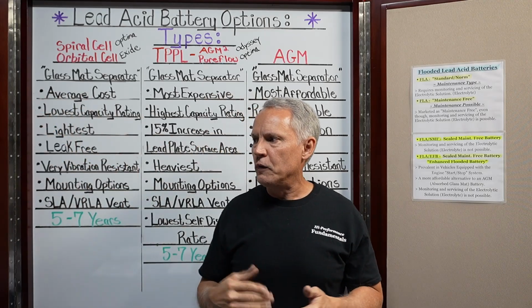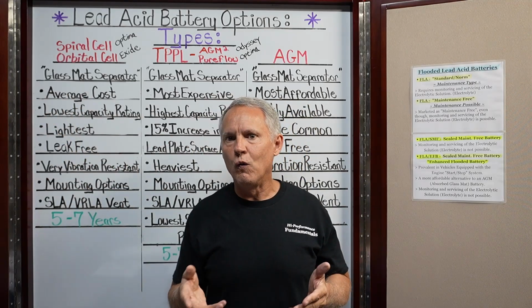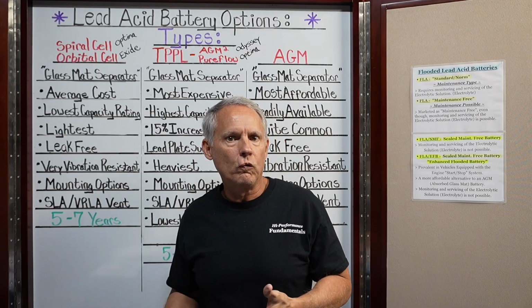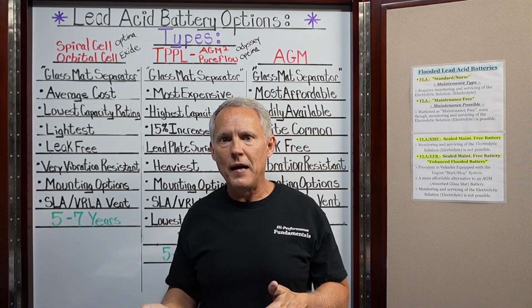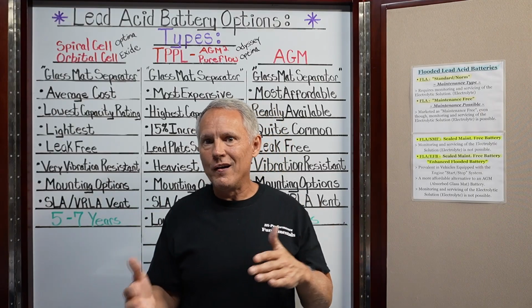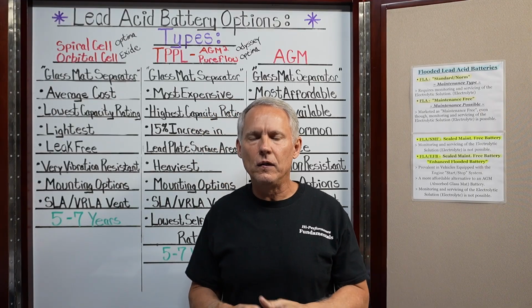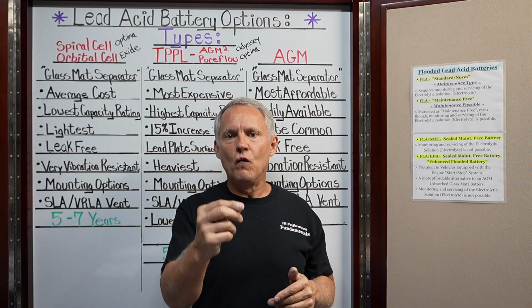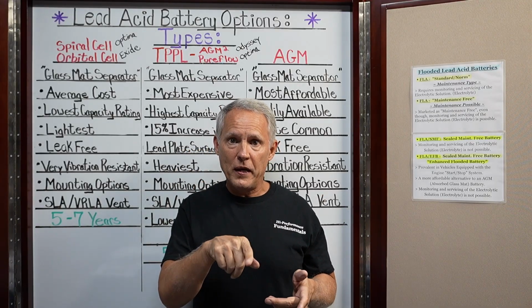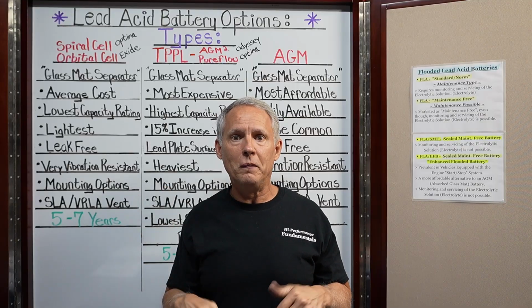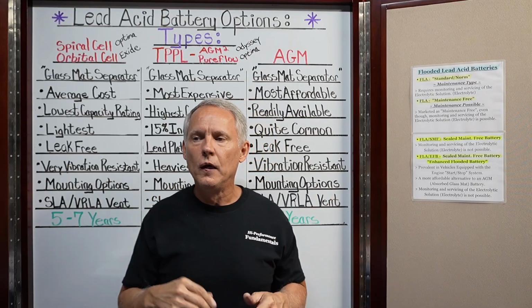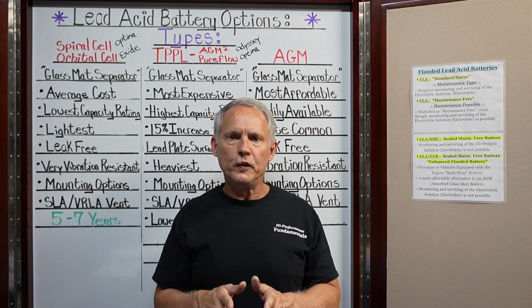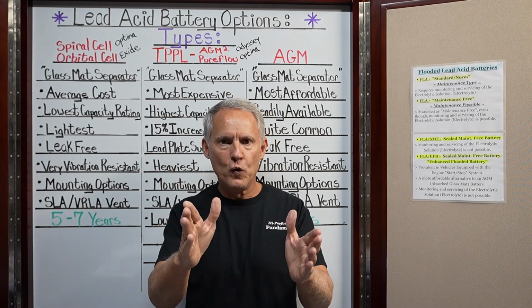So now, instead of 14.7 or 14.8 volts, what you may need is 16 volts to properly charge that battery, somewhere in that area, 15.7, 15.8. And just so you know, that recommended voltage can be found from the battery manufacturer. They will specify what they consider to be the vehicle charging voltage. So the problem is this: your alternator, your generator, won't properly charge that battery. What do you do about it?